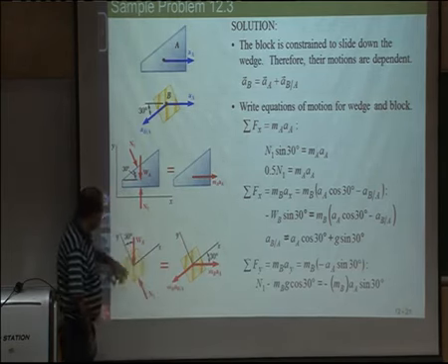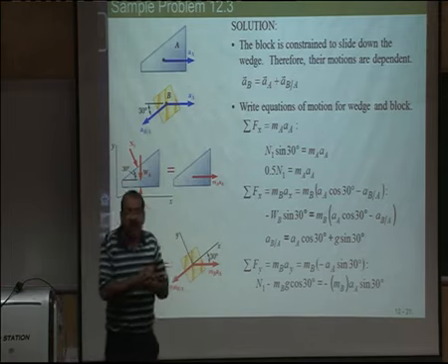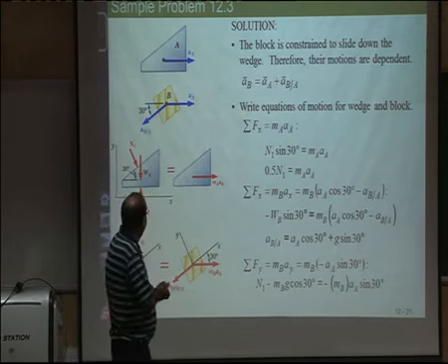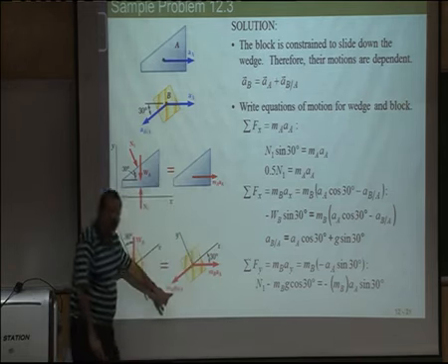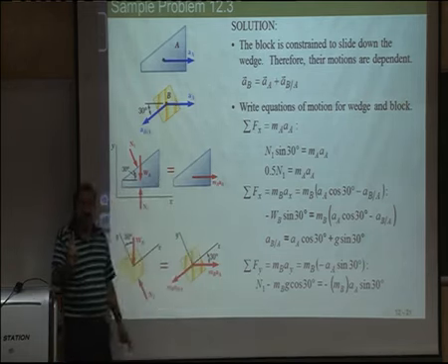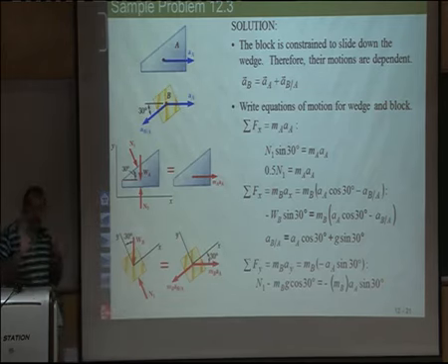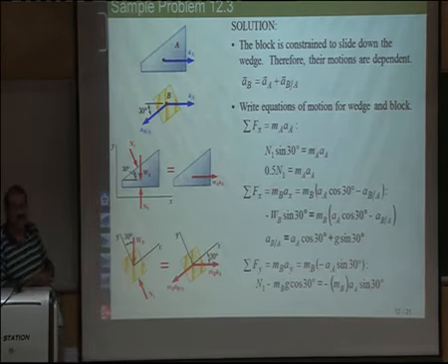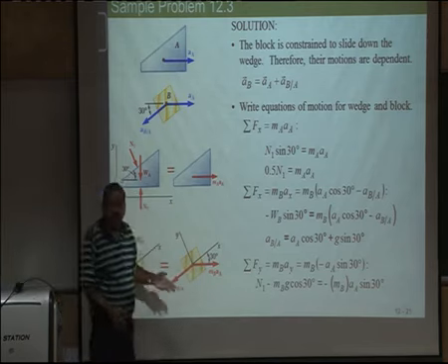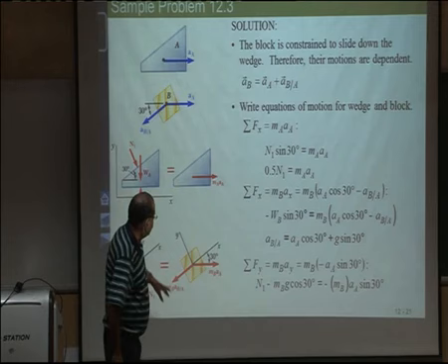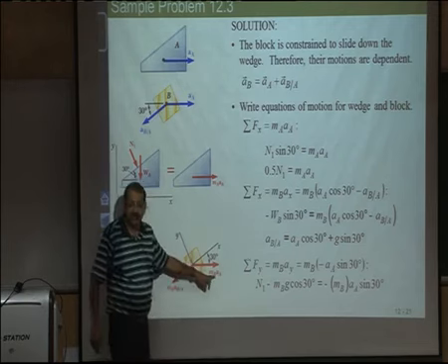So now one more scalar unknown has come, its direction is known. Now when we count, we have the required number of equations and unknowns. Which are the unknowns? Acceleration of A, acceleration of B with respect to A, two scalars, N1 and N2, four scalars, and we have four equations. So writing this acceleration in this form helps, makes life easy, because acceleration of A is itself an unknown.